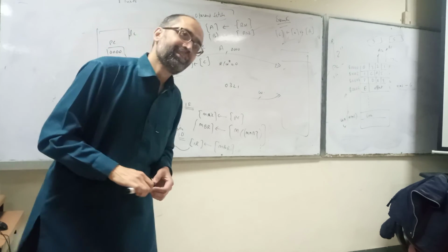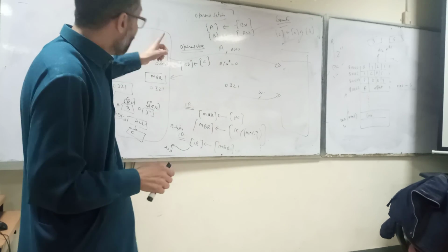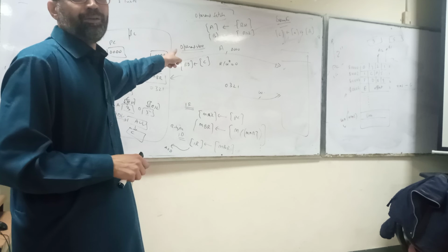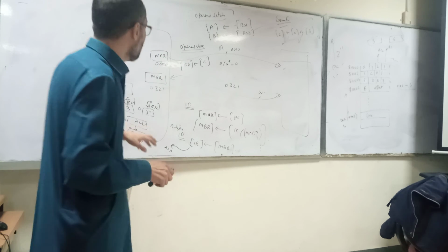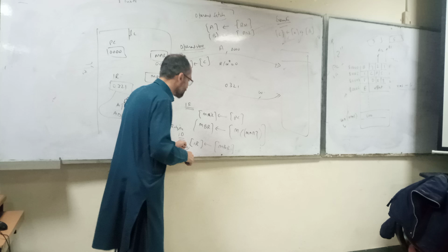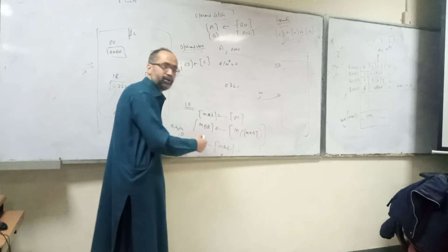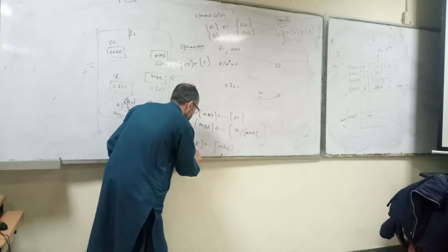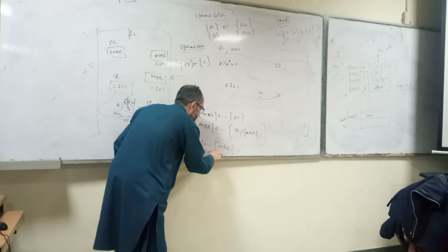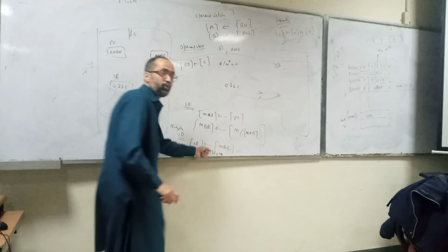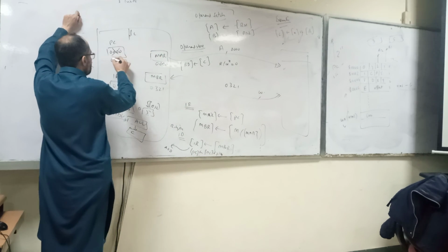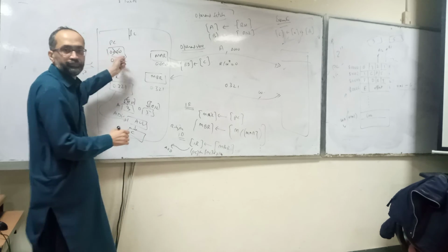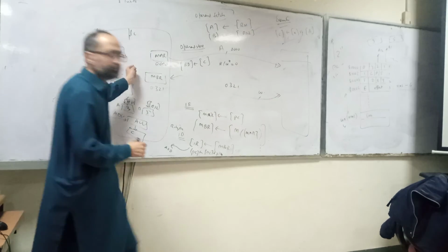But before doing this, the microprocessor should point to the next instruction. You can do this in the instruction decode stage, because it's done. So now you can update the PC: PC is equal to PC plus size of instruction. If the size of the instruction is 2, it will now point to 2.